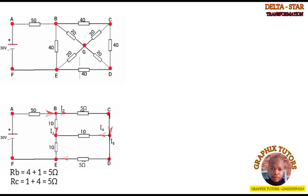If you look at it closely, it still looks complicated, but there's a way out. We have 3 resistors that are connected end to end. That is the 5 ohm resistor, the 1 ohm resistor, and the other 1 ohm resistor are connected end to end. Even though they look rectangular, they are connected also in what? In delta formation, because when you see 3 resistors connected end to end together, you can transform that into what? Into a delta formation. So let's do that.